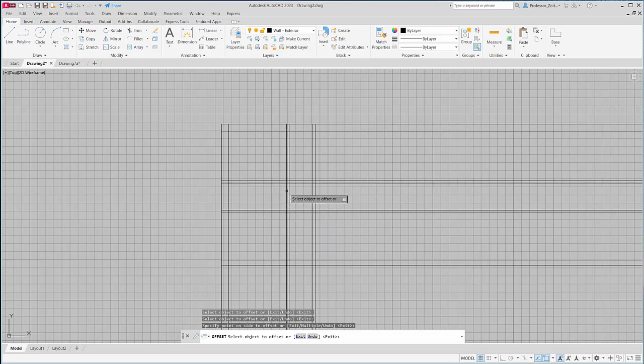You'll notice that the doorway here is this section that's 3'6", but the rest of the lines I don't need. So I'm going to trim these off here. I don't need these, and I don't need these. And this is where the actual opening is, 3'6". The other side of this has a door, which is 2'8", and we'll calculate that afterwards. I'm just cleaning this drawing up so it makes it easier to see, because we've got some other values that I'm going to have to adjust here.